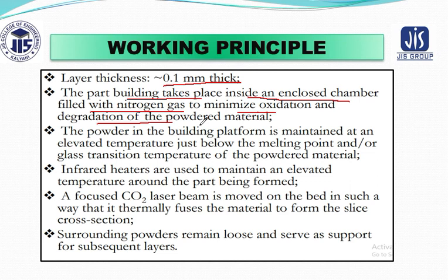If the powder is open, it will come in contact with oxygen or the impurities present in the atmosphere. To avoid this degradation and minimize oxidation, the entire part is built inside an enclosed chamber filled with nitrogen gas. This is very important to remember.